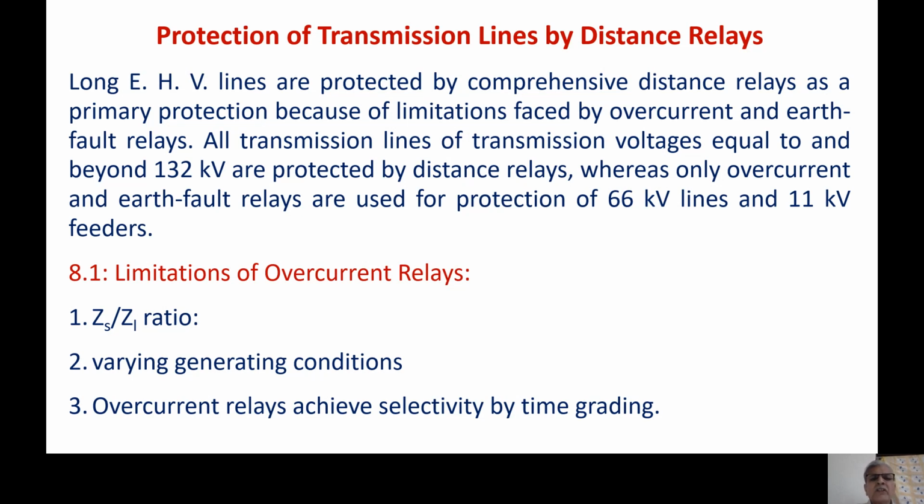It is a general practice to protect very long extra high voltage lines of 132 kV and onwards, that is 220 kV, 400 kV, 765 kV and so on, by distance relays. 66 kV and 11 kV lines are usually radial feeders, and to provide distance protection for such lines is a costly affair. The general principle of